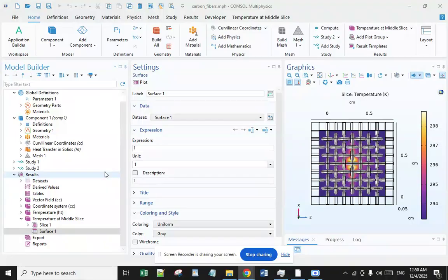For the measurement of the longitudinal thermal diffusivity, the fabric was partly placed on the hot plate and partly left hanging out of the plate, as in a cantilever plate setup, with a thin support at the end so the fabric would remain flat during the experiment. The camera faced the free thin side of the fabric between the hot plate and the support.